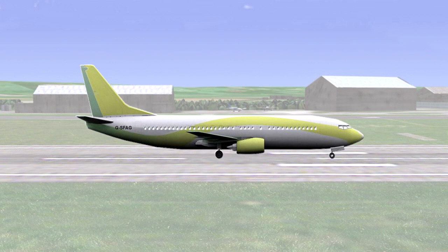Let us now consider the action of the drag force during landing. You may recall that there are several forms of drag. The main types of drag are parasite drag and induced drag. However, whilst the aeroplane is on the ground, during takeoff and landing, wheel drag must be considered alongside the aerodynamic drag just mentioned. The aim of the landing is to bring the aeroplane to a stop safely within the confines of the runway. In order to decelerate, sufficient rearward directed forces need to act on the aeroplane. Consequently, in addition to reverse thrust, aerodynamic drag plays a very crucial role in landing.